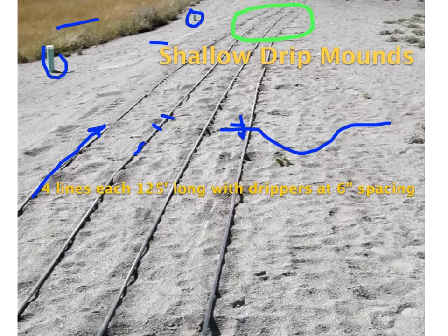Otherwise, as they drain, the air vacuum relief valve, which is up here, allows air to be drawn in fast enough to not risk sucking dirt into the system. The other reason is, of course, you'll get more water here, but it's going to be very small if you've just got a small little sag.